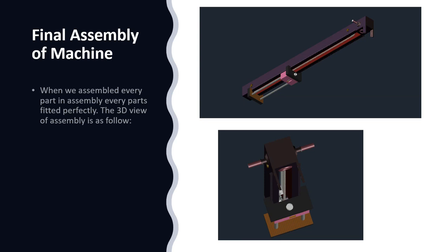The sliding assembly basically consists of the sliding weight and two rods that fix the height of 0.76 meter, and also inside we have the chain connected with the stopper. That stopper engages with one of the levers of the bell crank mechanism, and when the bell crank mechanism touches the upper part of the sliding assembly, it is disengaged automatically and drops freely, and penetrates the rod into the soil.